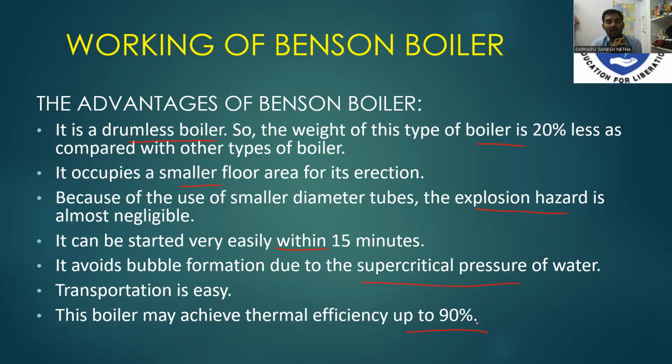The advantage is that it is a drumless boiler. By removing the drum, we can reduce the weight by nearly 20 to 30% compared with other types of boilers. Because it is small in size, we can reduce the installation area, and also because it has small tubes,